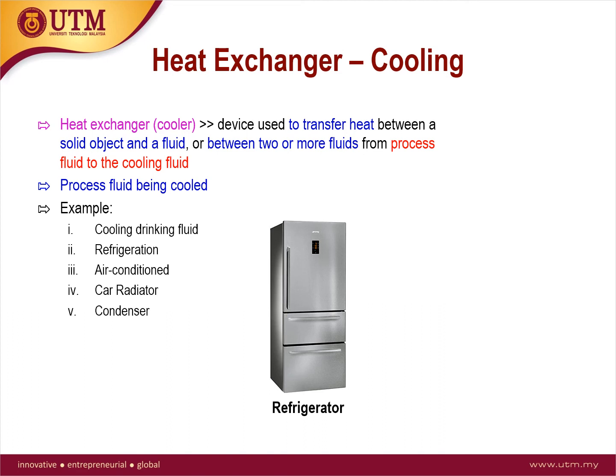The chilled water is supplied from a chiller that is potentially located very far away, but refrigerant must come from a nearby condensing unit. When a refrigerant is used, the cooling coil is the evaporator in the vapor compression refrigeration cycle.